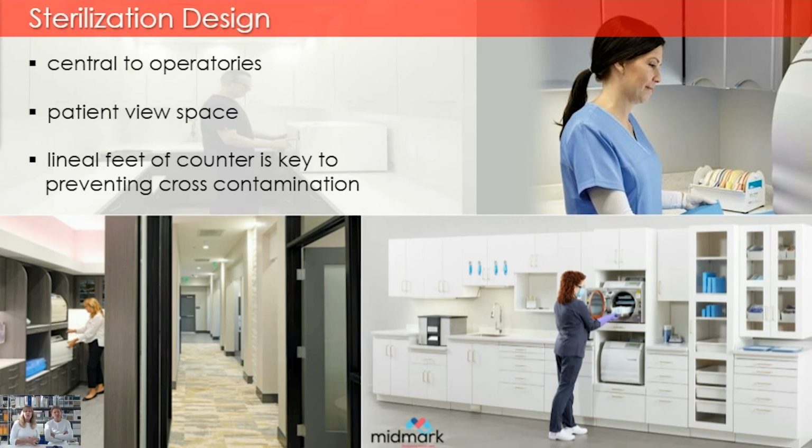So when we're designing, we want to see that sterilization area central to all the operatories. When I say central, I want to have it about 2 to 3 operatories of walking distance away. If you get much farther than that, we're starting to become inefficient. And that's another reason for the floor plan that you saw where we had the L and the mirrored L. That's the reason we have 2 entries into that sterilization area. So any assistant accessing that sterile area is not going to be walking any more than 3 operatories away.